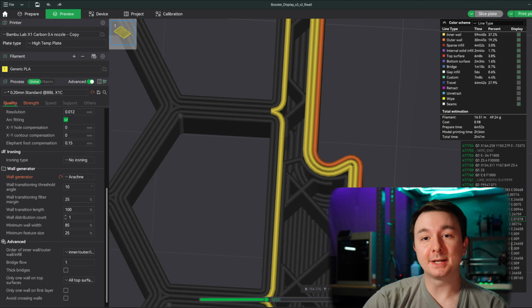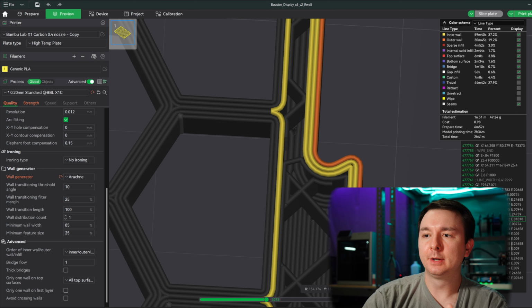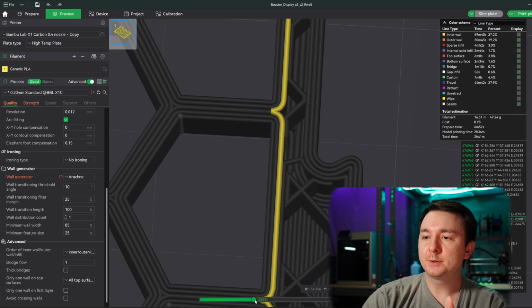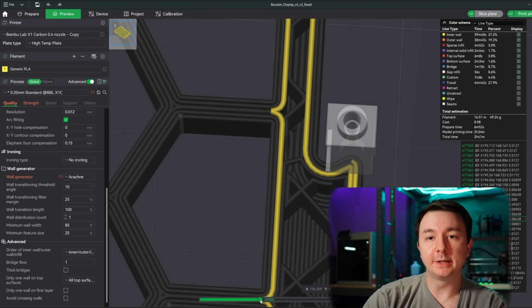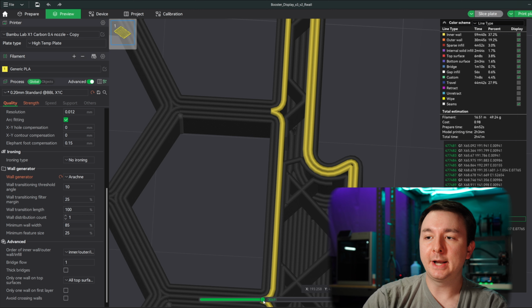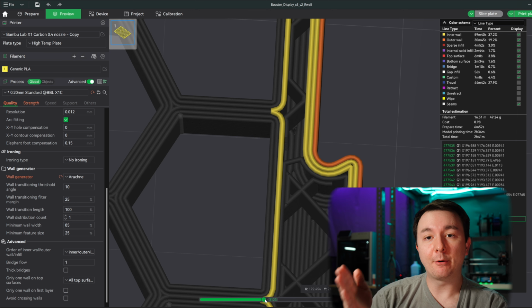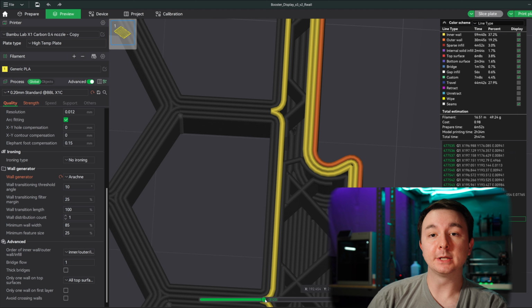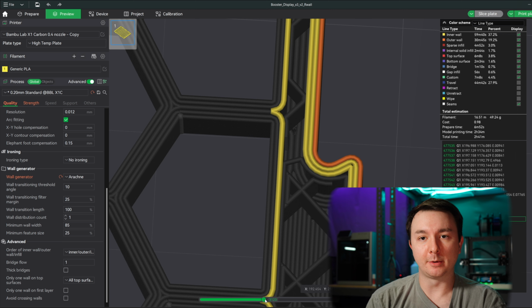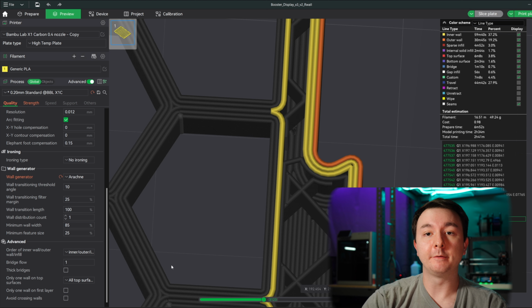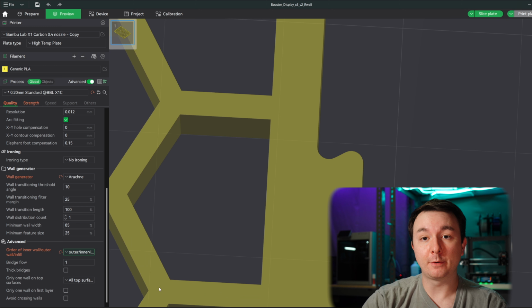One problem that this can have is error stacking outwards from your print. So if this first perimeter is slightly wrong, slightly too thick or slightly too thin, as it prints outwards, that error will translate to the outer perimeter of your print, and you can see that even though it was an inner perimeter. If you want the outermost perimeter of your print to look better, you can choose to print the outer perimeter first.